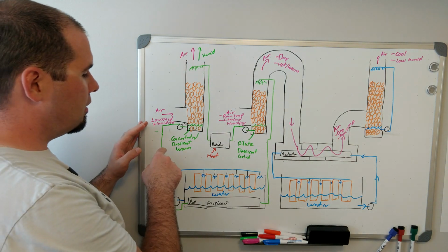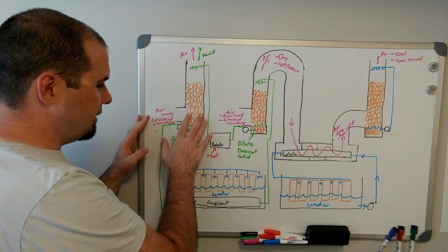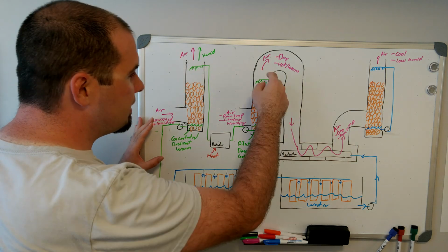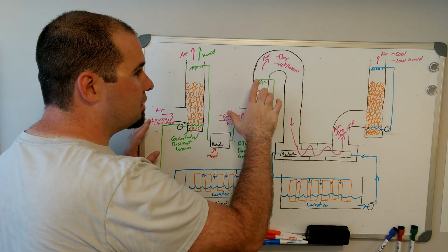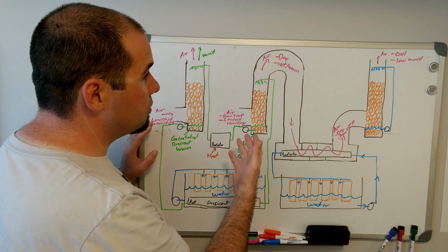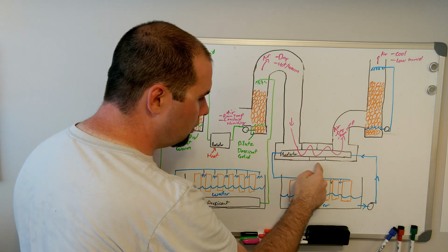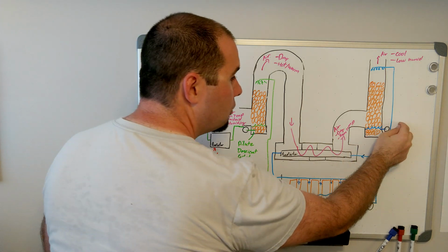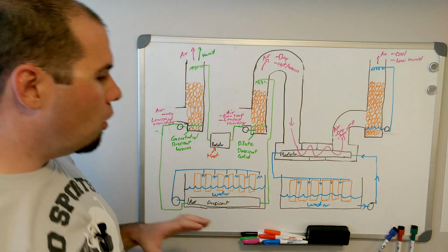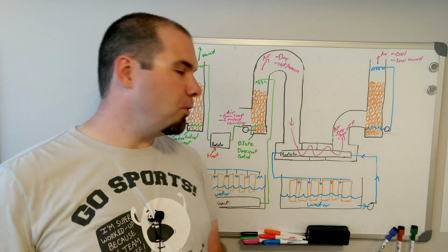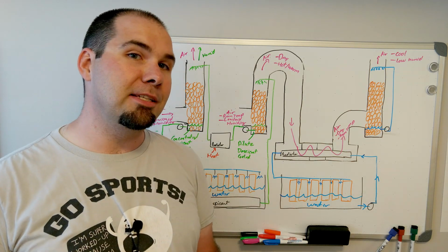We are essentially concentrating our desiccant with this. We cool the desiccant so that we can use it in a regular heat exchange, regular process to dry the air, which results in hot-warm air, cooled to room temperature, then cooled below room temperature while putting back humidity into it. So hopefully between his video and my quick whiteboard explanation, you now fully understand how this process works.